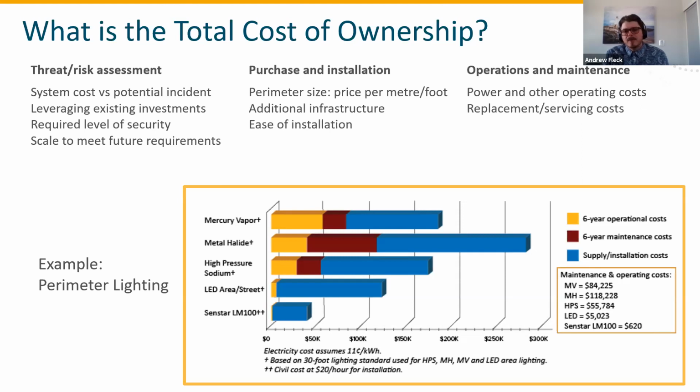The reality is the upfront costs of the equipment are not always the answer to what makes something the best solution. The amount of time we take to deploy something is a big factor in what we recommend as well. As a prime example, anytime a perimeter exceeds 4 kilometers in Canada, I immediately begin to look at fiber. That's because the ease of deployment of fiber optic, the time that we now save, outweighs the extreme cost delta between a copper fence sensor and a fiber perimeter fence sensor.